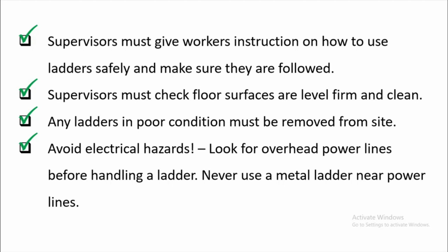So if the insulation is already damaged, then there is a leak of electricity or voltage from that damage, especially if there is moisture. Then if you are using a metal ladder, it will immediately conduct the electricity. So make sure that before you use the ladder, you avoid such electrical hazards.